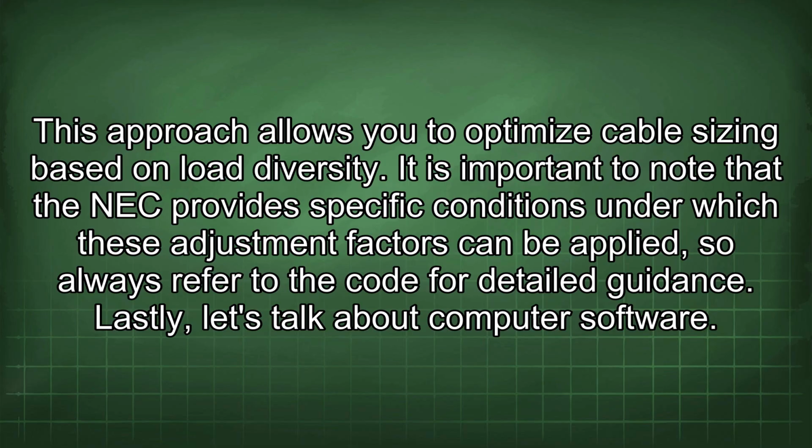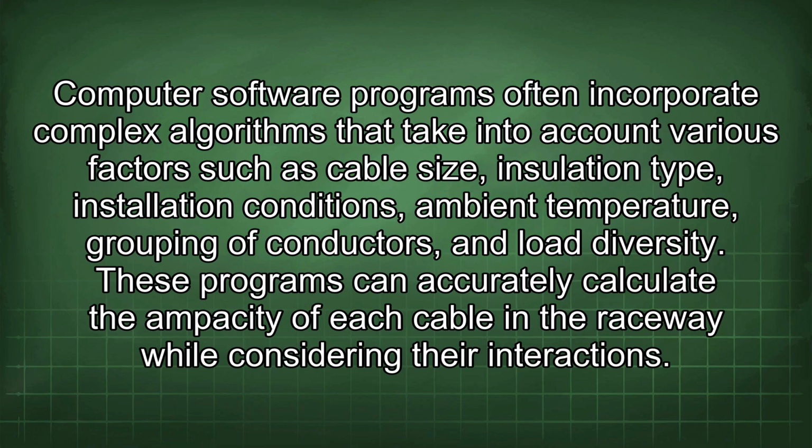It is important to note that the NEC provides specific conditions under which these adjustment factors can be applied, so always refer to the code for detailed guidance. Lastly, let's talk about computer software. Computer software programs often incorporate complex algorithms that take into account various factors such as cable size, insulation type, installation conditions, ambient temperature, grouping of conductors, and load diversity. These programs can accurately calculate the ampacity of each cable in the raceway while considering their interactions.